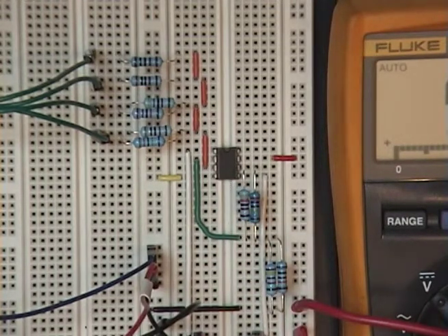The question I've been putting off is, what is the gain to implement in the op-amp circuit? We've seen the value of logic 1 coming in, so let's decide what we want to do with the output. Let's say I want the output to be as many volts as the binary value at the input indicates. So if my digital input is binary for 5, I want to see 5 volts out. If it's 2, I want to see 2 volts.